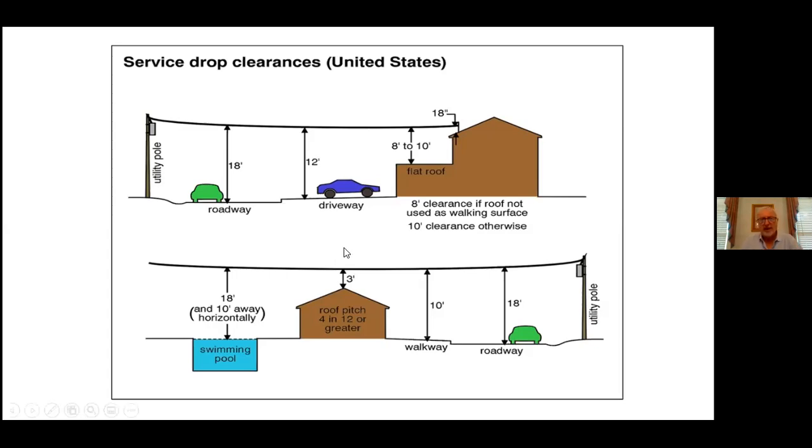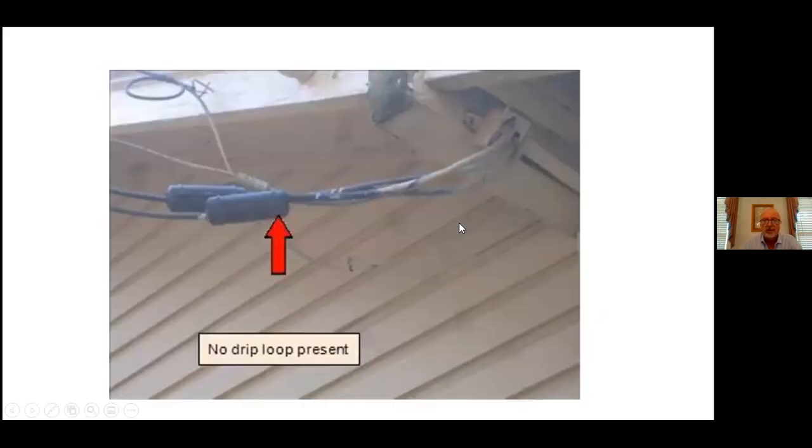We'd probably recommend some clearance there, some cutting back of the trees, to try to stop a problem before it starts, perhaps in winter when some of the branches might break off, or in the summer if there's a big storm, break off and hit the wire and damage it, therefore causing a power outage.